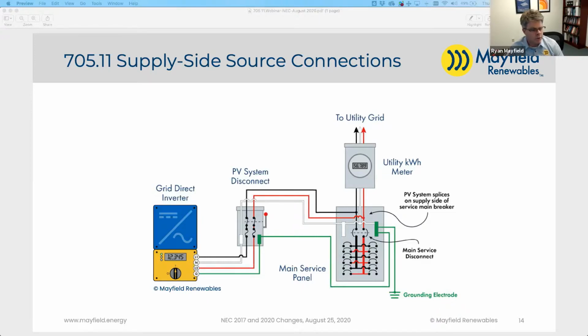And I remember one specific site where there was a second AC aggregation panel that fed a second one. There were a number of individual inverter breakers on the bottom of this panel, and then this large combined one at the top. And the large combined one at the top actually was tripping due to all the heat that was being built up. So unfortunately, I don't have a great, here's your perfect answer for this, but doing some sort of modeling, trying to figure out what those temperatures are. Part of the really hard part is it's going to be variable.